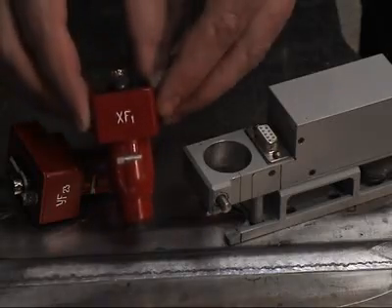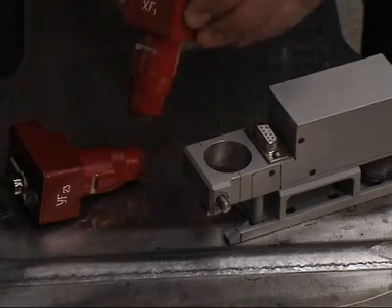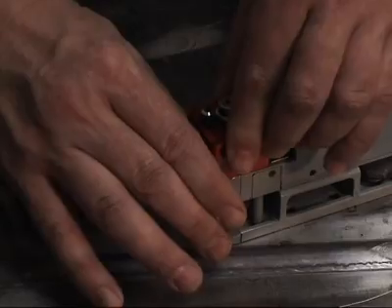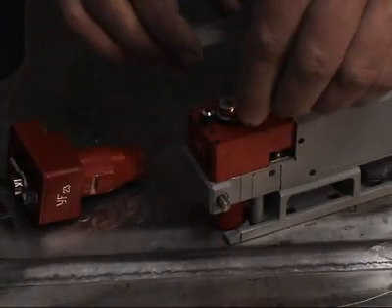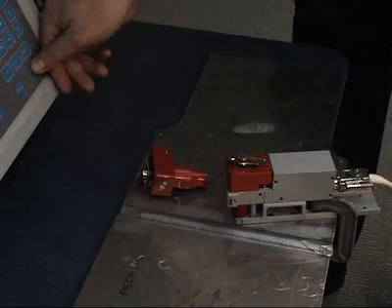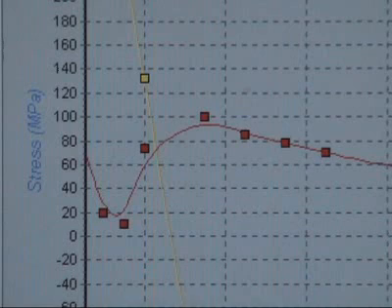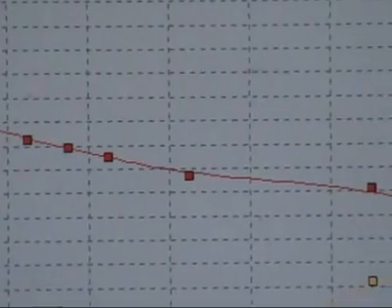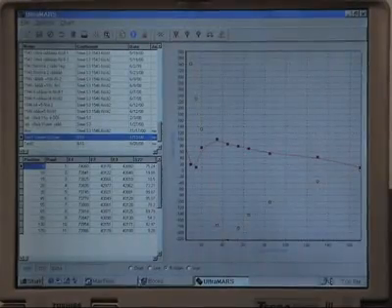The next step is installing the gauge to measure the velocity of the longitudinal ultrasonic wave that is perpendicular to the material surface. The results of these measurements are used for residual stress computation at the point of measurement, measurement of ultrasonic wave velocities in a number of other points, and finally plotting the distribution of residual stress after all measurements are finished.